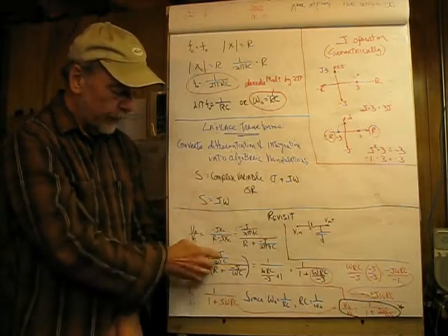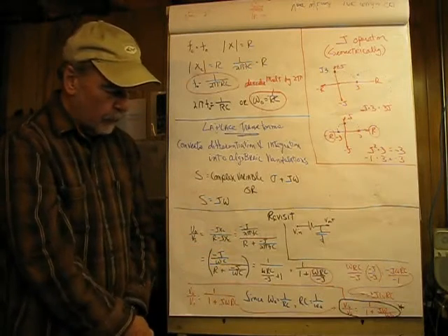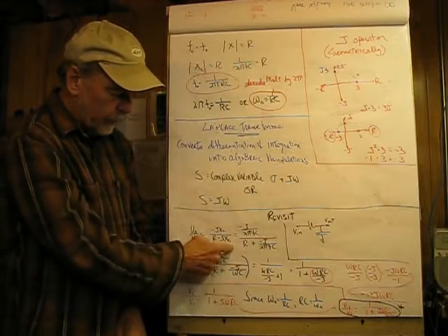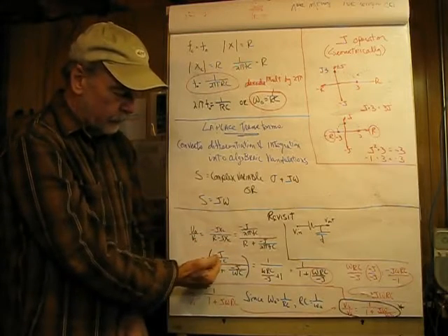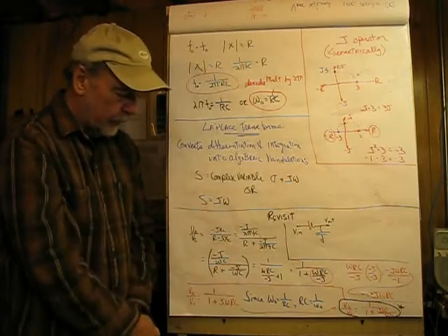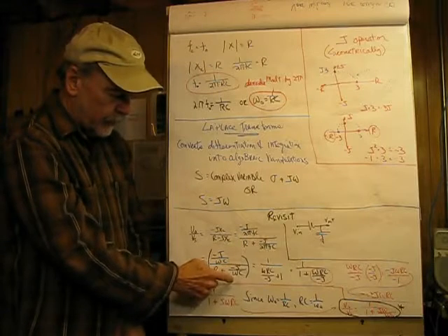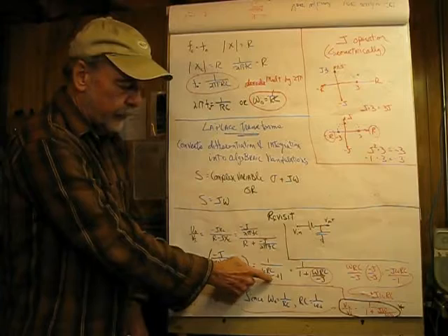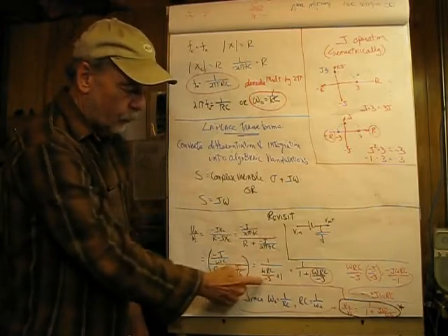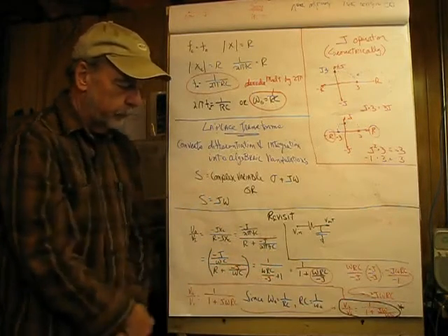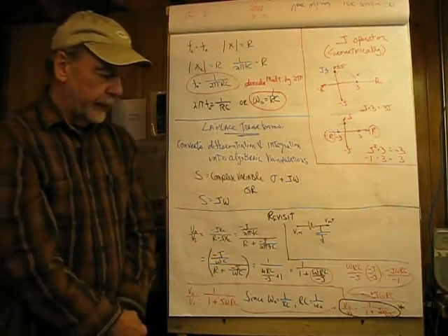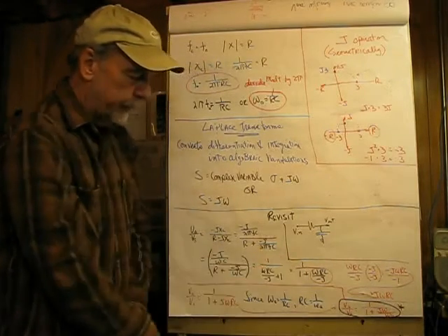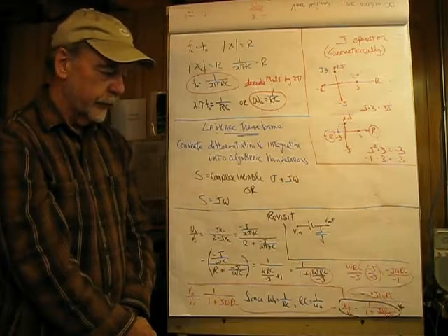So what I want to do is clean out the numerator here, and when I do that I get 1. So omega C divided by negative j times this would give 1. And then in the denominator we would be picking up this term, omega RC over negative j, plus 1. And this would be the plus 1 here. So writing that in standard form, we would have 1 over omega RC divided by negative j.